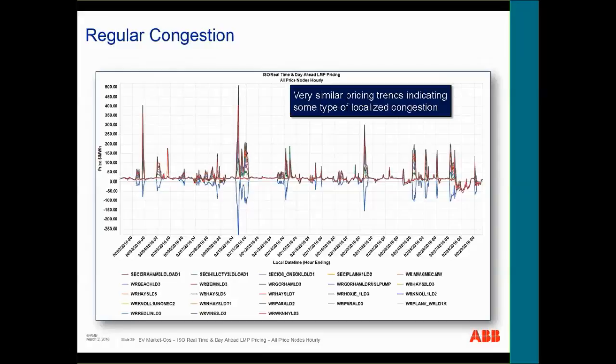So when we visualize that pricing on an hourly time frame, now we're again looking at that February window, but we're looking at all those individual nodes on a chart. It's very, very obvious to see the congestion, and you can see the spread that we were talking about in that different area where we have prices skyrocketing as high as $500 for a megawatt hour, and on the other side of that constraint dropping down to below negative $250 for a megawatt hour. Being on the right side of this constraint can really help the lifespan and the revenues of a project.